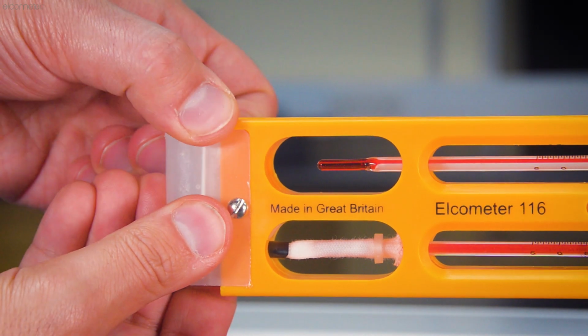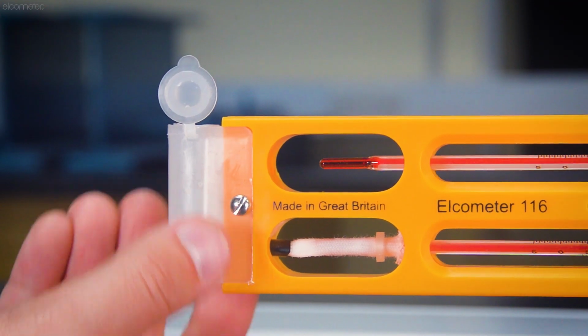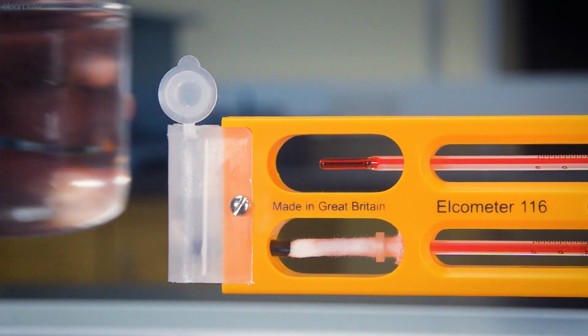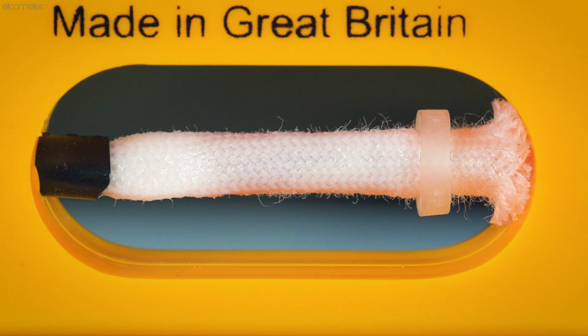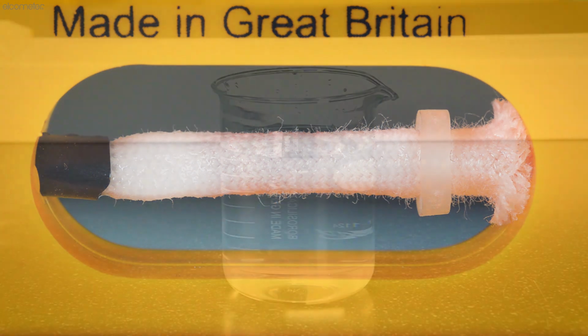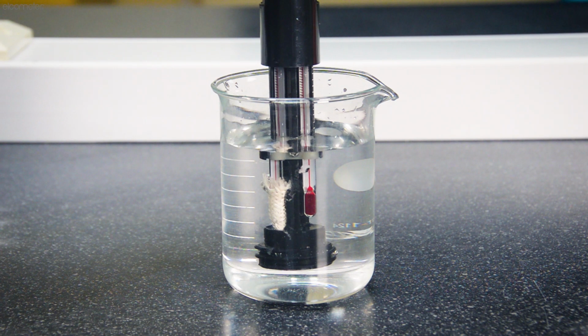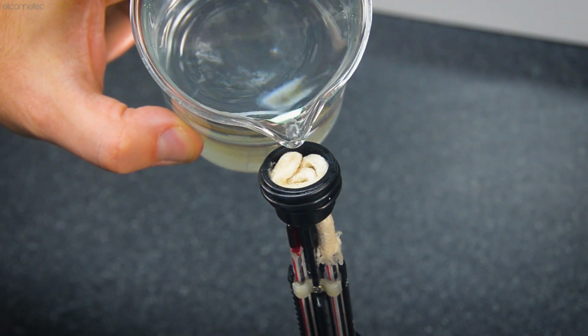To prepare the wet bulb thermometer, distilled water is added to the reservoir of the hygrometer, and this saturates the wick. In the case of the Elcometer 116C Sling hygrometer, you're actually instructed to fully submerge the thermometer bulbs in distilled water first to ensure the wick is saturated, and then fill up the reservoir.